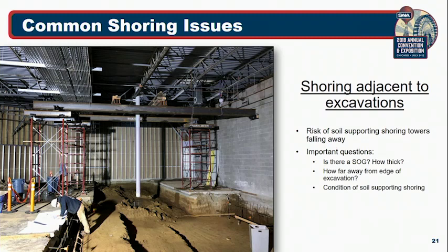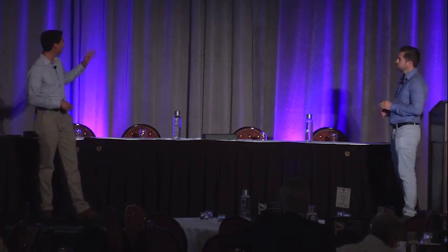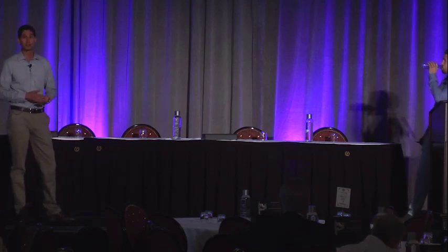So having a good idea of what's going to be going on around during the project and what your scaffold is sitting on is pretty important, like whether your scaffold is going to be sitting on a slab on grade, and if so, how thick is it? If it's not and you're sitting on dirt, is it well-compacted dirt, or is it really loose and you're going to need to start looking into a bearing pad, things like that. In addition, all these things put together are going to determine how far away from the edge of any excavation you're going to need to be to maintain the solid foundation of your scaffold.